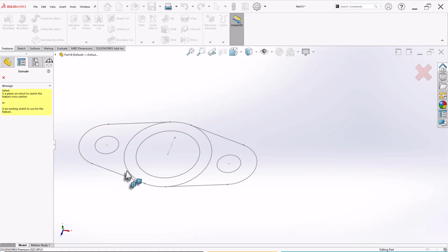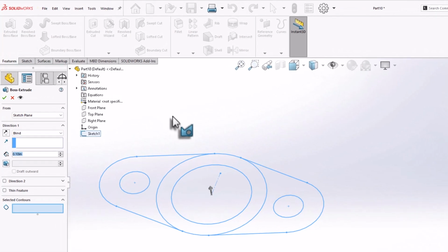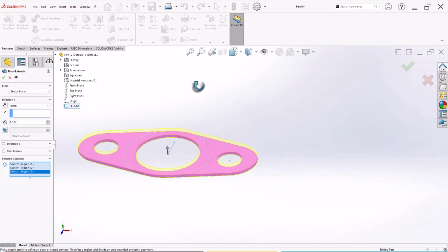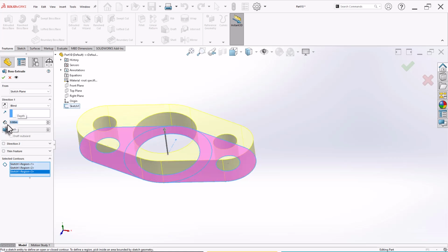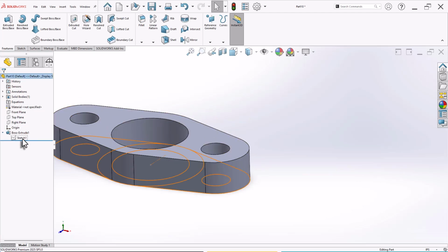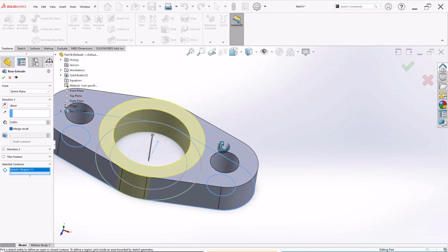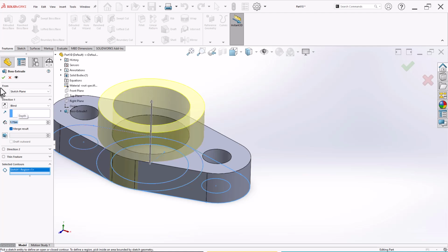Now let's create the extrusions by using the contour selection. So select the extrude feature and you can also select from here. Okay. Now it is asking which contour you want to select. So look at very carefully. We are going to use this part, right? Now here, what is the depth? Depth is 0.88. And click OK. Again, select the same sketch, extrude again. This time I'm going to use these common regions and I'm going to extrude by 1.75 and click OK.